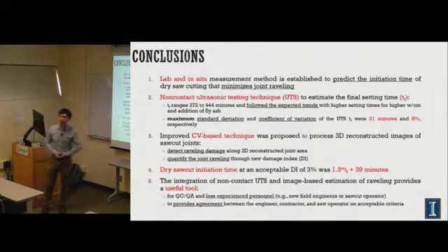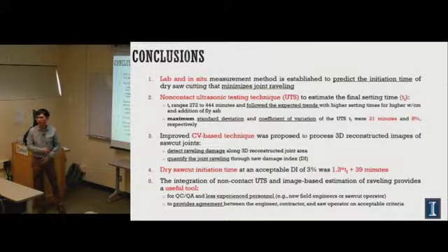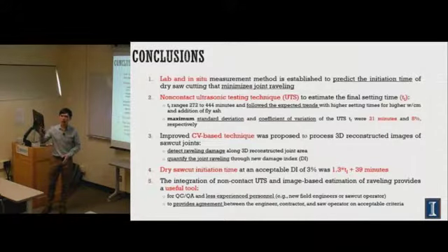So imagine that the engineers, like contractors, come to the site and then say, this is a good saw cut. But this is too relative. How good it is, we don't know. So this technique will help them to quantify it. At least, in the contract, I say, as long as I have 3% of the damage index, it's acceptable. And then the saw operator says, okay, I cut it, I check it, it's 3%, so I commence on the cut for the long concrete pavement, right? So it's going to save a lot of cost at the beginning for both of them.